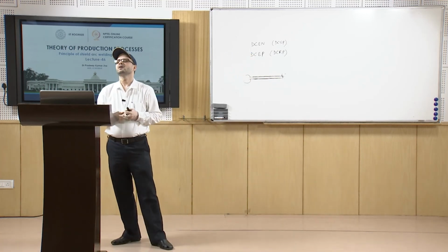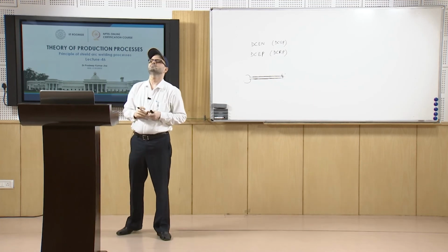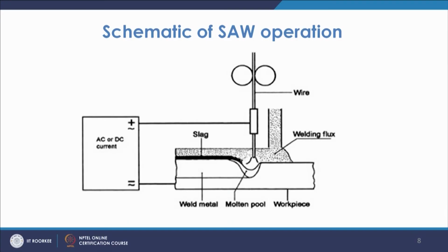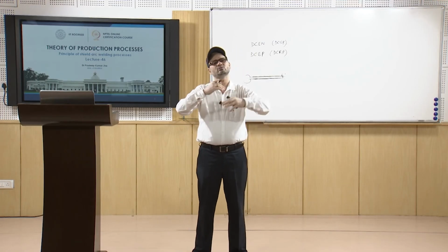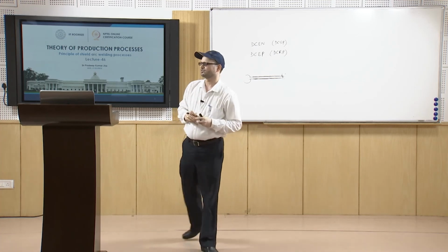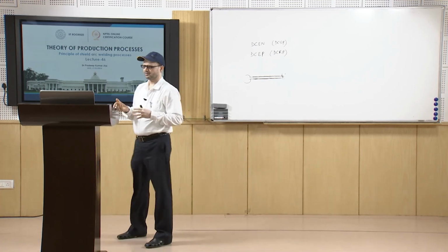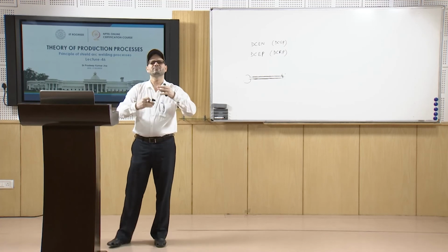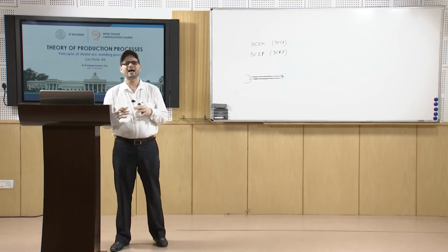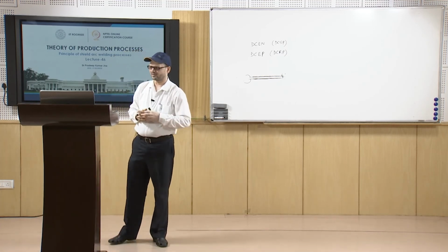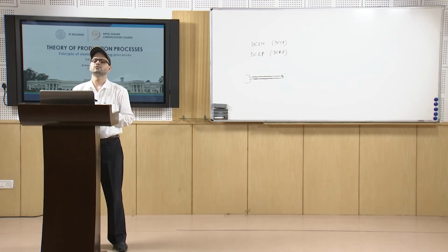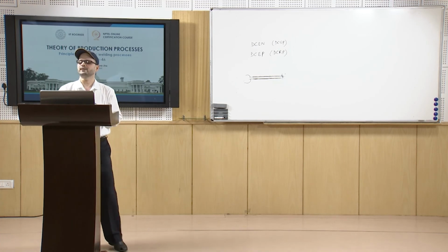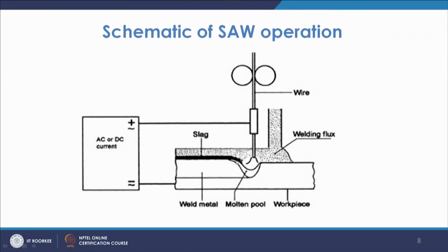So, you can see the submerged arc welding here, the deposits can be at quite a larger rate depending upon the value of current. You can use a larger value of current in these cases. Depending upon the type of deposit or type of penetration, you can have either larger current or even a change in the voltage values. Now, as you see, this is a slag.